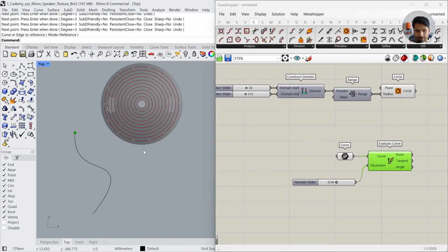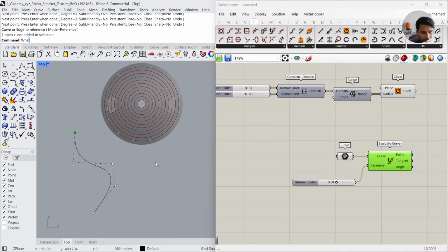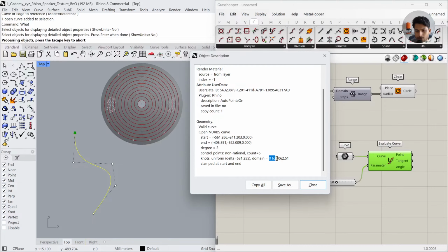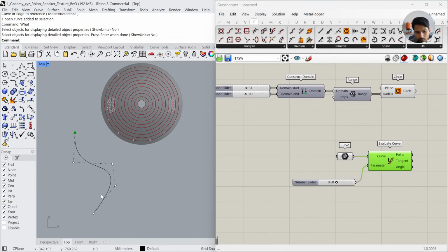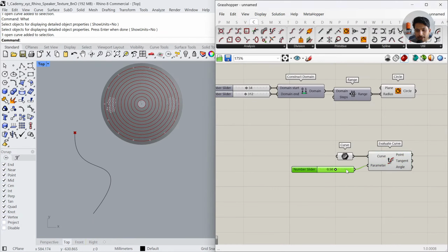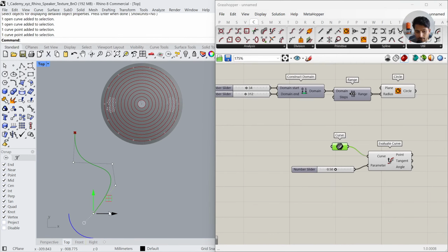The problem is, by default, this curve numerical parameter called domain would be between two random numbers, 0 to, in this case, 62. It's basically the length of the control polygon. But that's not relevant here. So what you can do is convert this curve, instead of 0 to a random number, from 0 to 1, so it's easy for us to make a point anywhere on the curve.